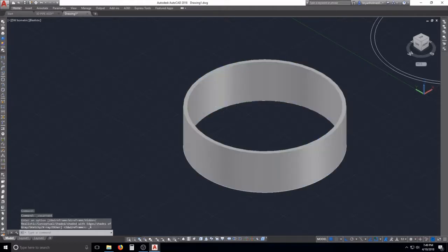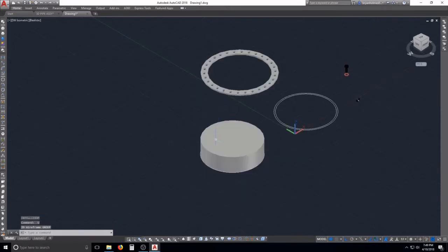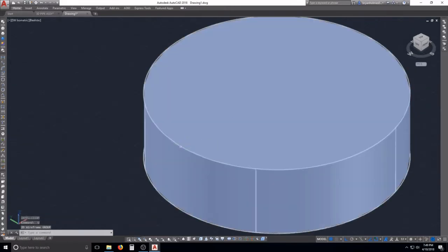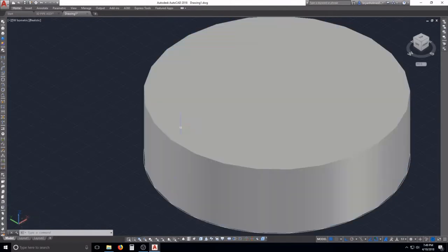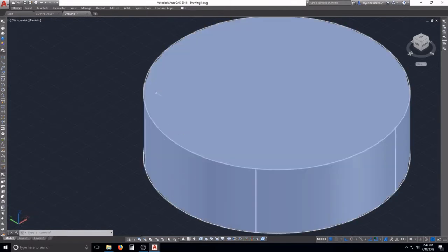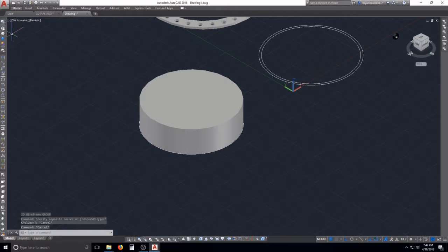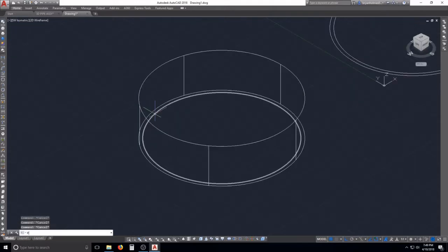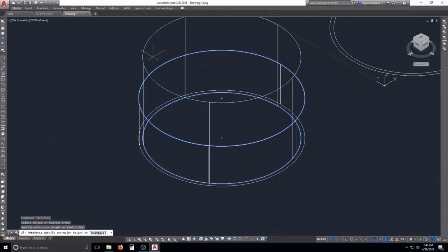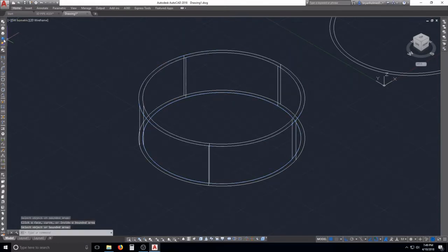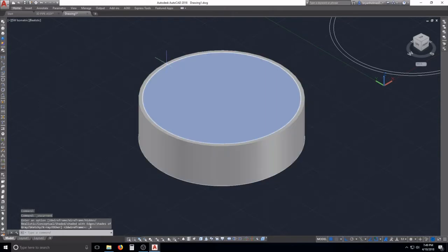Because if you did not do that, see how it's one solid circle, and so basically we extruded, press pulled the other one up, and because it had a smaller diameter, we erased the inside and left only the wall, the distance between the inside and the outside circle, which in turn gave us the pipe. And again, to establish that, press pull, that'll pull out and up 12. And again, just to prove my point, even though we know we have it up there, see how it's coming in.